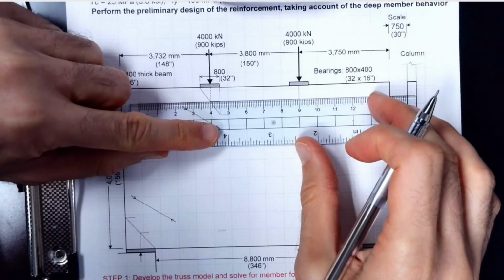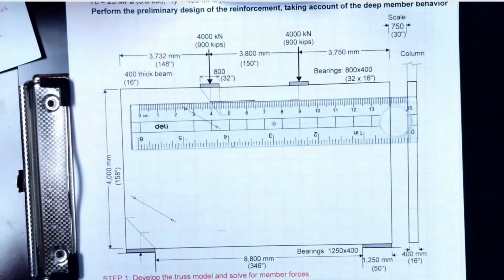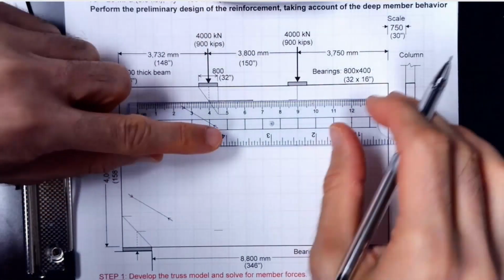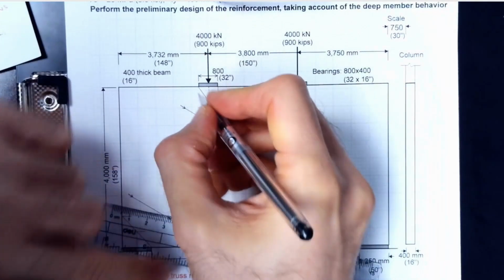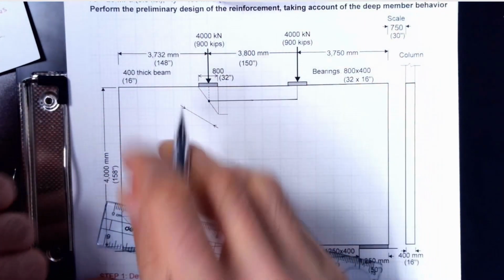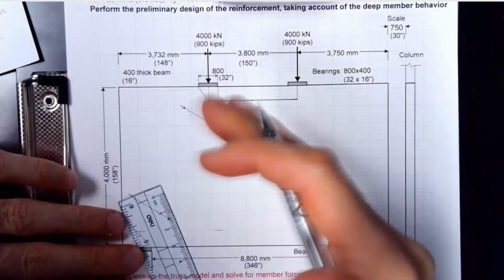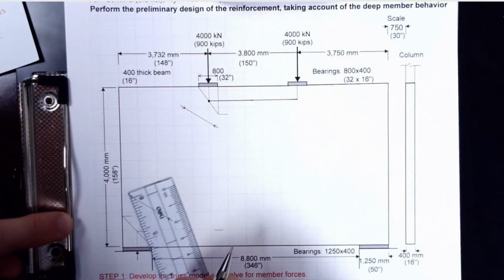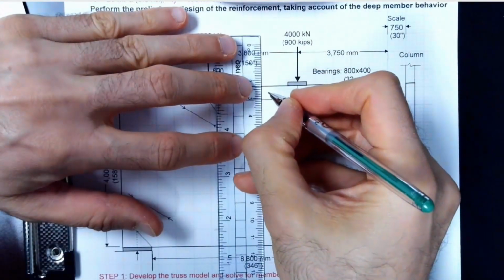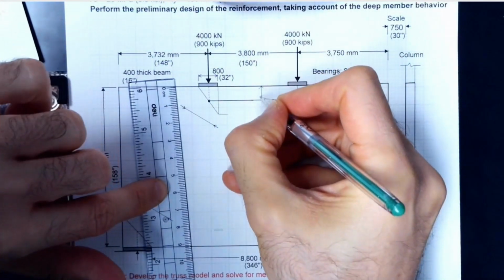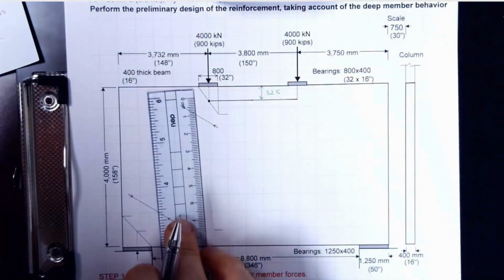I have some guidelines to make this to scale, so you can see the line, which is the top compression strut, which is this one. This is the node. At that point, I'm only showing half of it, so I'm not going to be solving the entire system. The distance would be 325, which is what I'm assuming, 325 millimeters.